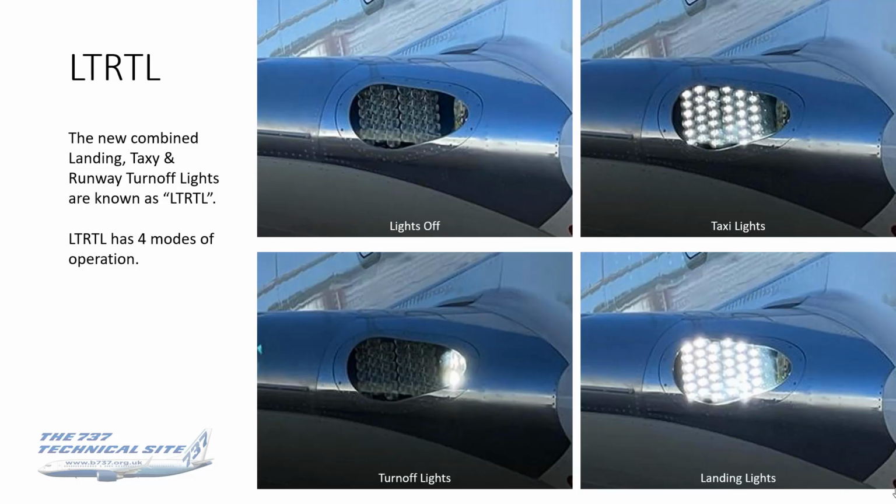Now, these new combined landing, taxi and runway turn-off lights, known as LTRTLs, have 4 modes of operation, as you can see there: off, taxi lights, turn-off lights, which you can't quite see in this picture, but they are pointing outboard by, I think, about 30 or 45 degrees, I can't remember exactly, and the landing lights facing full forward. Basically the taxi lights are just a lower intensity version of the landing lights.